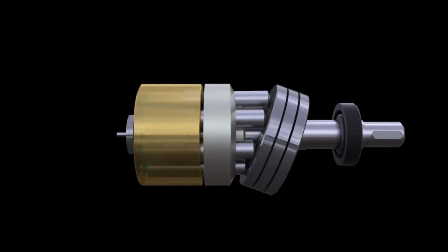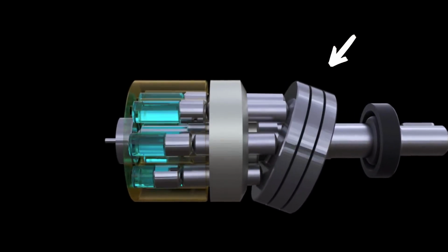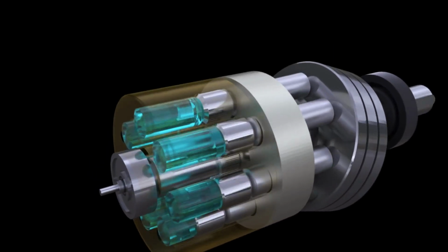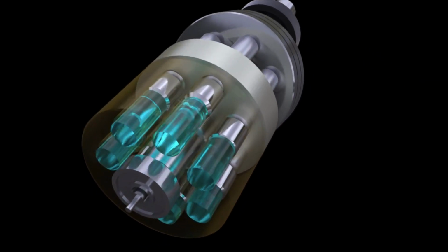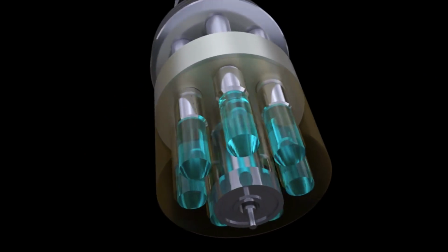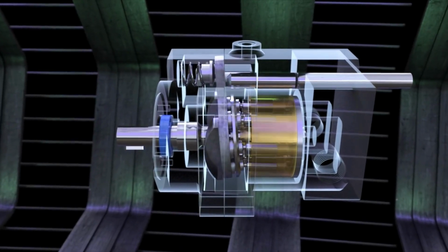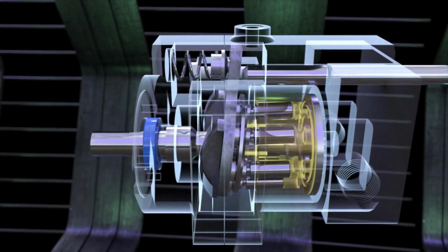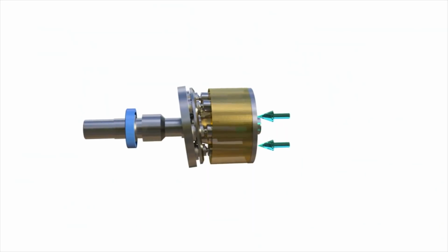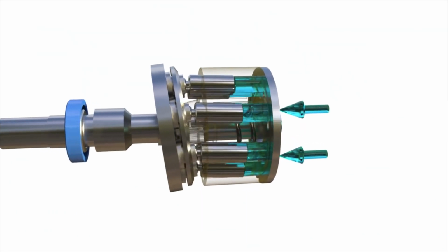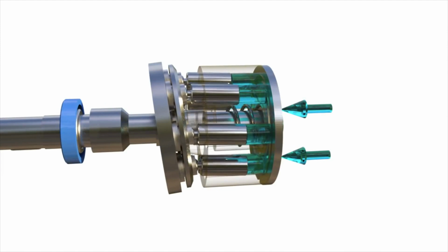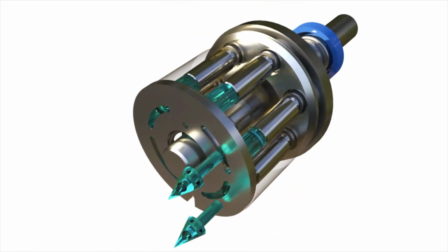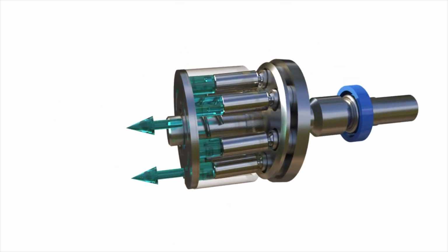Now let us look at the function of the swash plate. A swash plate is used to change the discharge of the pump. As discussed earlier, it will change the discharge of the pump when the angle of the swash plate is varied. By changing the angle of the swash plate, we can change the stroke length and hence the discharge. When the swash plate is perpendicular to the pump axis, then the discharge will be 0. The discharge will increase with the increase in the swash plate angle from this perpendicular to the pump axis.